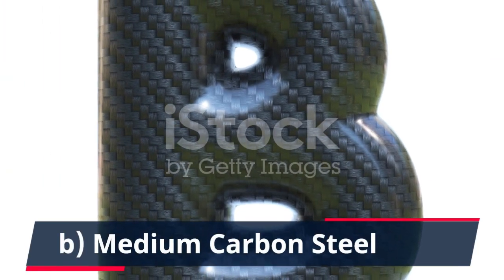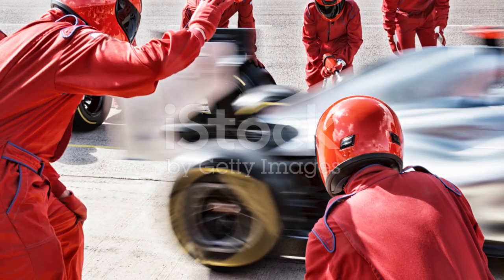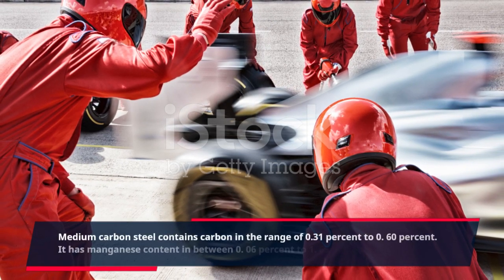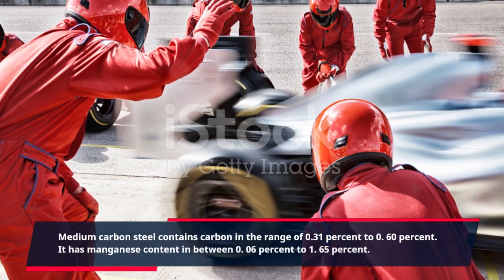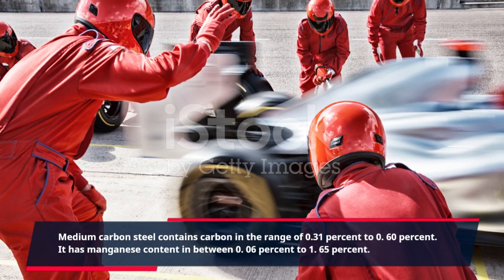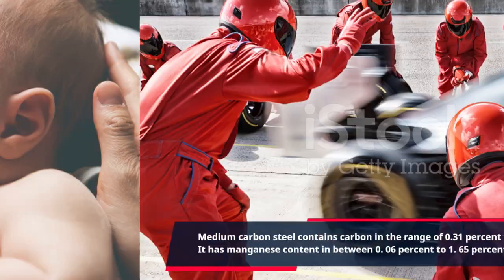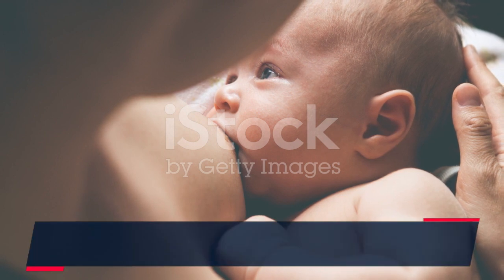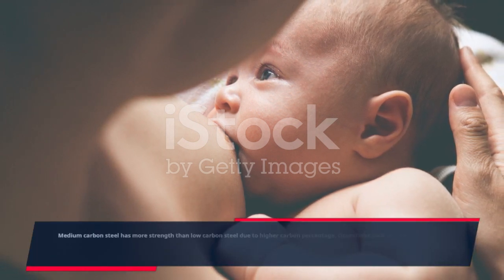B. Medium carbon steel. Medium carbon steel contains carbon in the range of 0.31% to 0.60%. It has manganese content in between 0.06% to 1.65%. Medium carbon steel has more strength than low carbon steel due to higher carbon percentage.